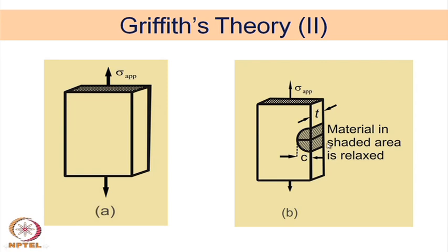We have seen it earlier also where we were considering sigma max. Here also a crack has been generated, and surrounding that crack we have a strained region where the atoms are not exactly in their equilibrium sites, but have been displaced from them. So, a strain field has been generated surrounding the crack.